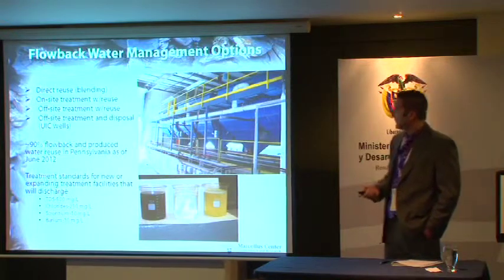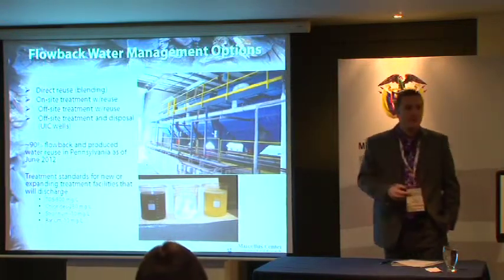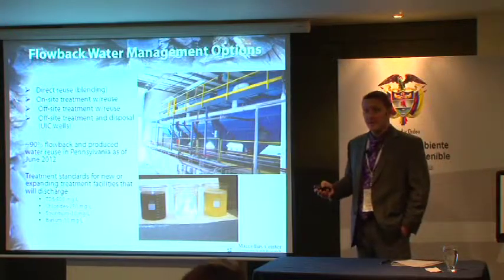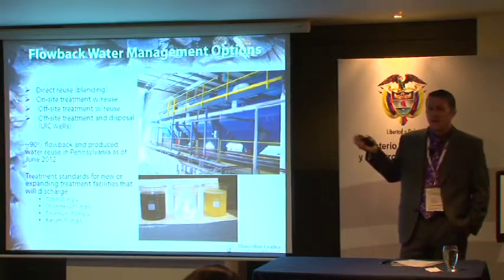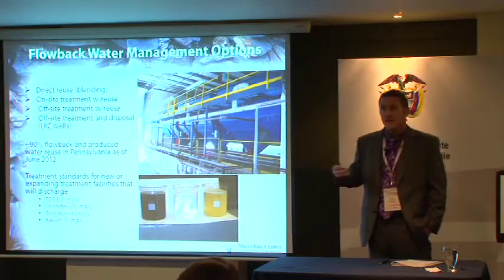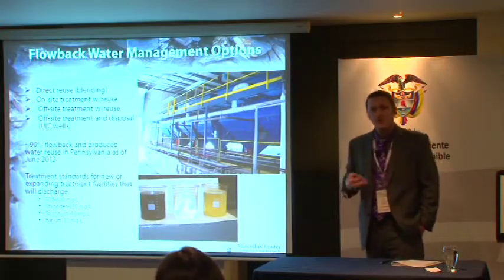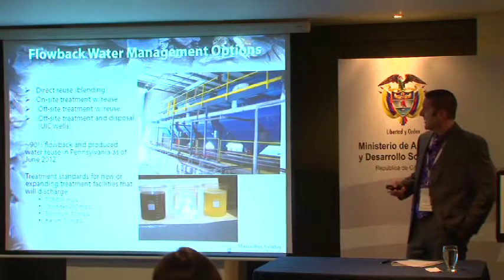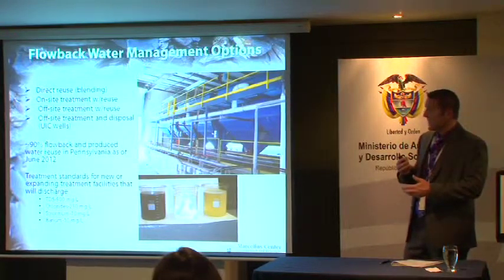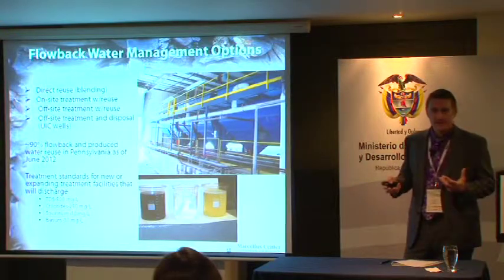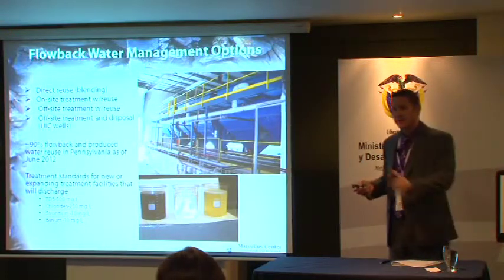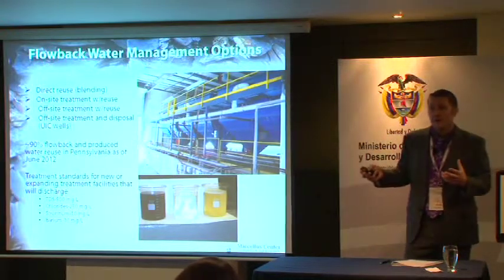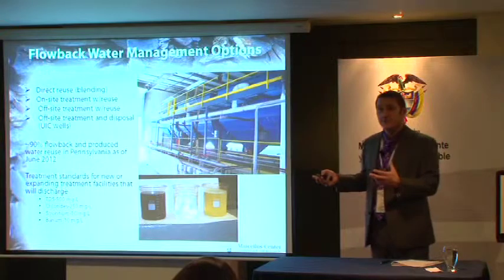So I want to cover the wastewater stream and what some of the options are to deal with these produced waters, which are going to have a relatively high total dissolved solids content and things like naturally occurring radionuclides and metals like barium and strontium in them. Again, what we're seeing is a lot of reuse of these fluids. Pennsylvania has really been a leader in innovating the reuse of these produced fluids.